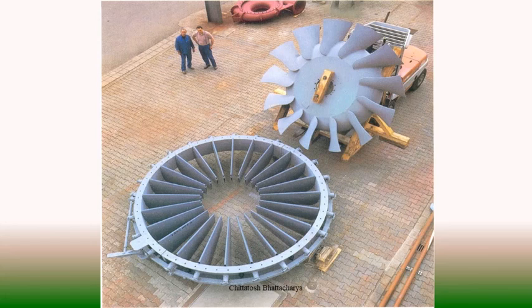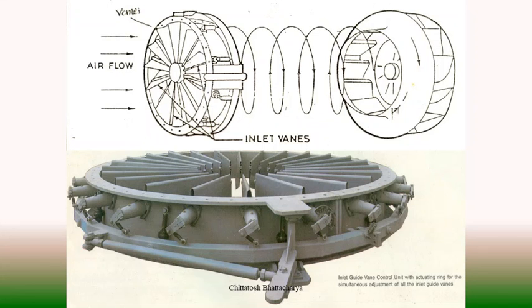Now these guide vanes are actually giving a swirling effect to the incoming gaseous fluid, and due to this swirling effect, whenever the gas enters the passage of the impeller, it gets radially discharged more quickly, and effectively the centrifugal force is utilized.